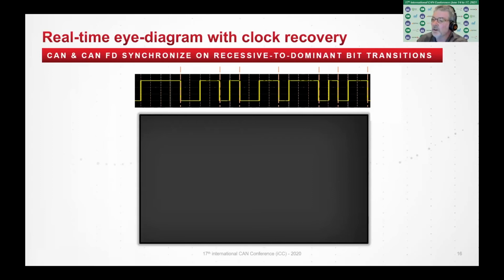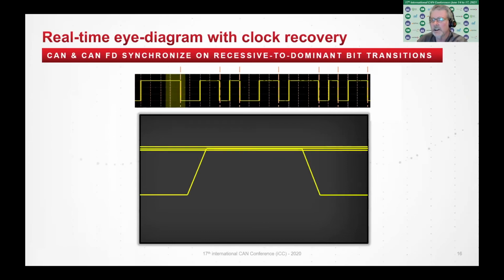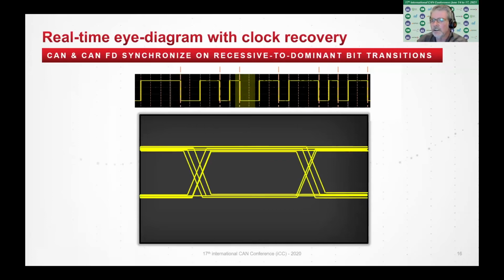And it's much more accurate than a CAN bus, each node's clock accuracy. The scope's time base typically has an accuracy of just a few parts per million, or it could be fractional parts per million. Once it has divided it up, then it steps down through the waveform, taking 2 bits at a time, and begins overlaying them to create the eye diagram.